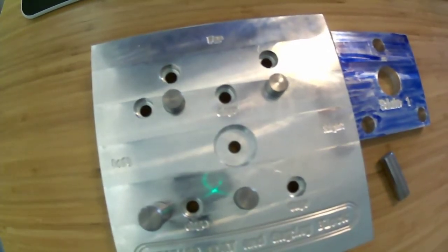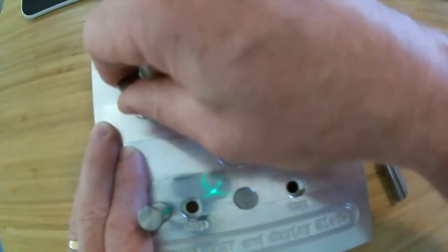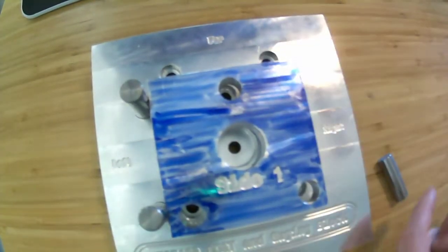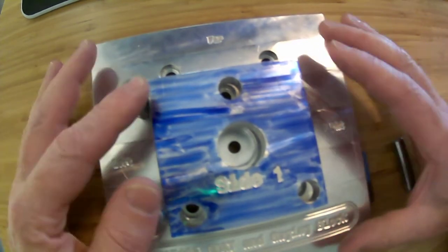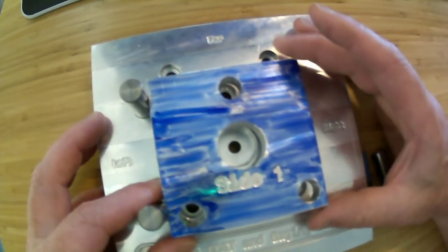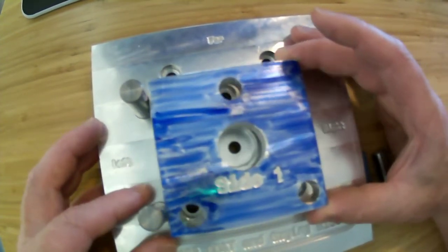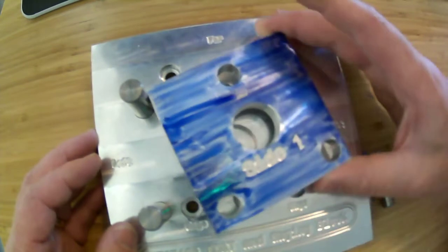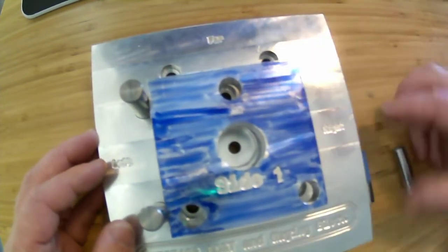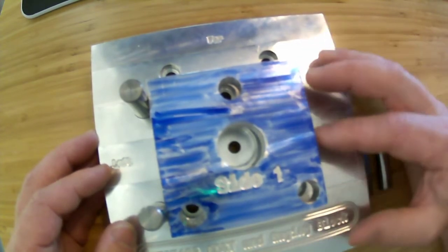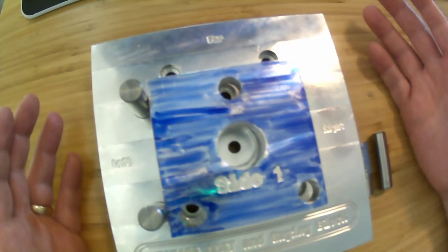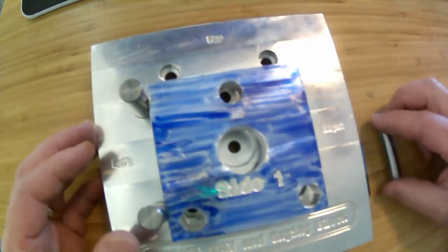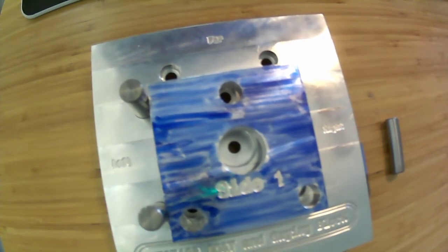Okay, there's 1. Here is another. These are really good tight fits to get precision, so it takes a little bit to put them together. So you can see that this is put together. How many degrees of freedom do I have now? I eliminated 3 the first time, and now I've eliminated translation in X, because I'm going to clamp it over here, and I've eliminated rotation around the Z-axis. So now I've eliminated 5 degrees of freedom, which means I only have 1 degree of freedom left, and that is movement along Y.